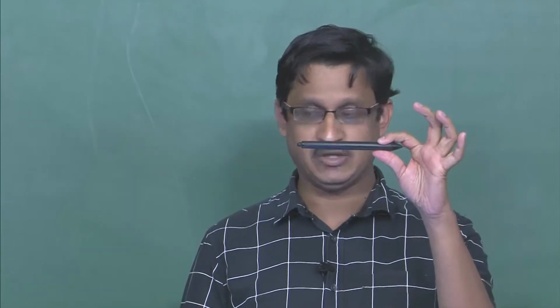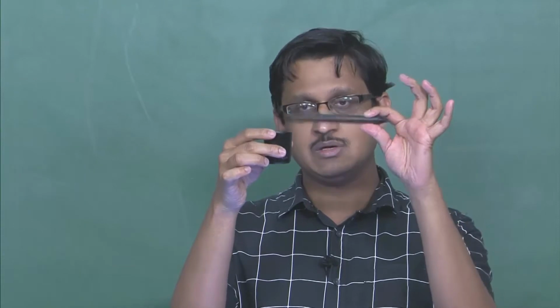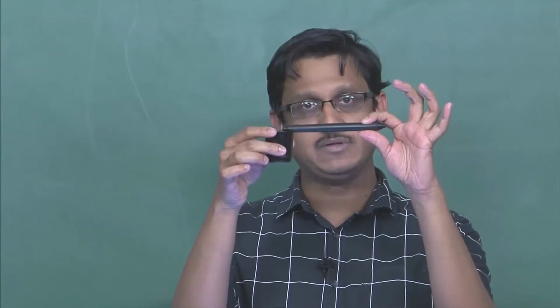So this module is trying to help you understand the basics of the Smith chart, the origin of the Smith chart, and let us begin by noting down a particular relationship between the generalized reflection coefficient and the impedance of the transmission line at any point on the transmission line. What is this generalized reflection coefficient? I know that if I consider a transmission line, and then I terminate this transmission line with a load impedance, then this piece is the transmission line terminated by this load.